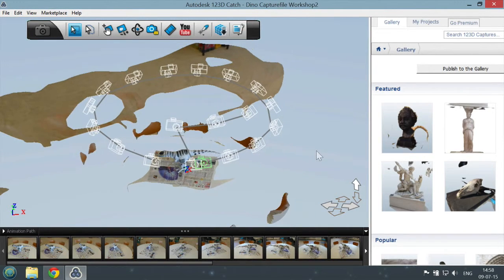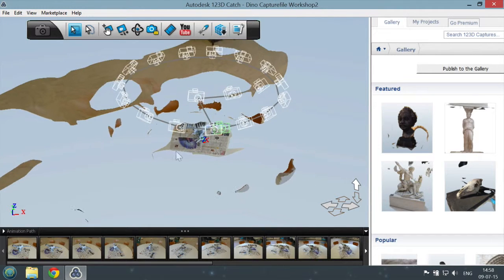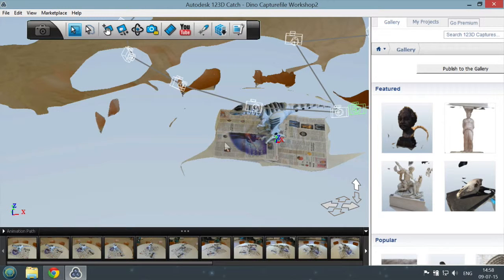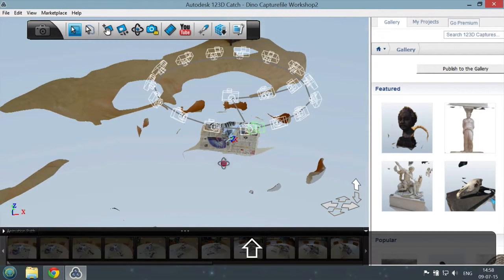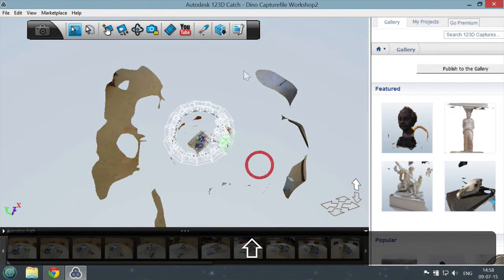In the first lesson I did a sort of a hello world regarding what you can do with 3D photogrammetry. I explained to you that you need some stuff under the object you want to scan, like a piece of newspaper, and don't put any shiny objects in the scene. That will not work.